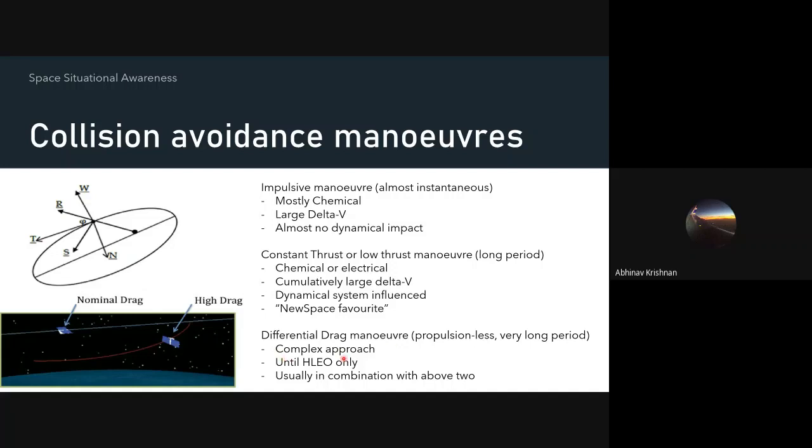And differential drag maneuver always acts in the T and W reference frame, because this is directly acting on and dependent on the velocity vector of the object. So that is why I mentioned T and W here. Anywhere else, a simple RSW reference frame would work.